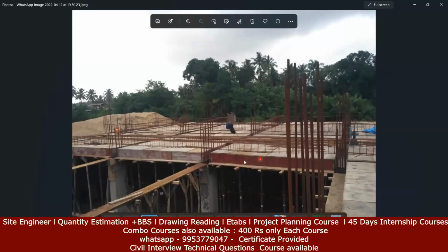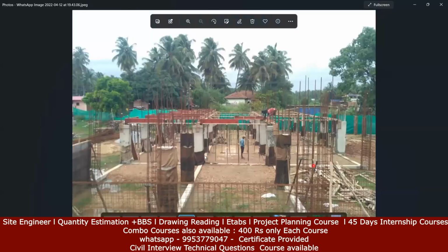So all these are your basement slab centering, all these things, the beam reinforcement, whatever we had seen, 16 diameter, 5 bar at the top, maybe 16 diameter, 3 bar in the bottom. Everything they have arranged practically on the site. And now you can get a better idea. See, this is my plinth beam, agree? And this was a column which I casted, and this is a beam bottom which I'm putting.